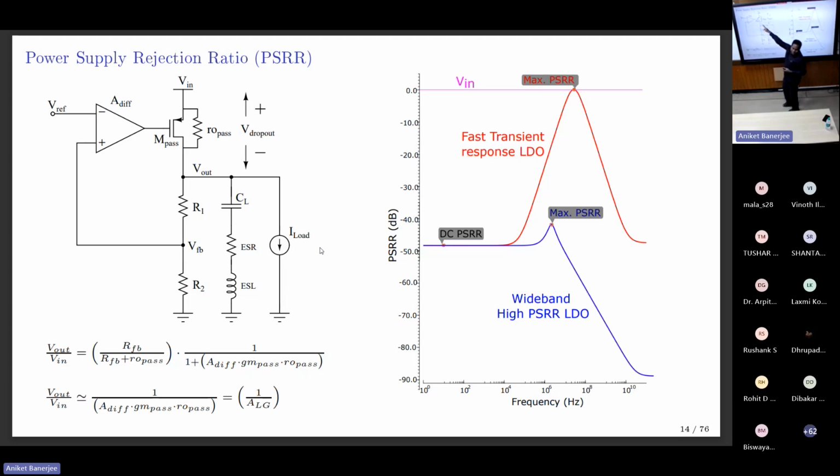This you don't have any control over. The input pole you don't have control over, right? Because this MOSFET is sized for this load current, and the CG load cap is fixed. So here you have the freedom to move the load cap. So all you can do is remove this cap to see how fast my design can go. This is all we can do.